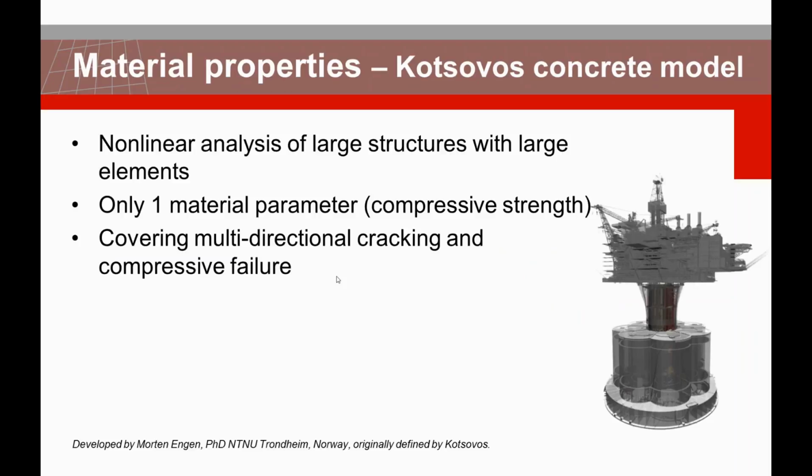Another model that we have at the concrete level, as I mentioned, is the Kotsovos concrete model. It is very useful based on the minimum input, that's a compressive strength, and you can use this in conjunction with large structures, like these types of platforms. As a rough number, when the size of elements is 1 meter or more, you can use this model. It gives you very good prediction of the failure.